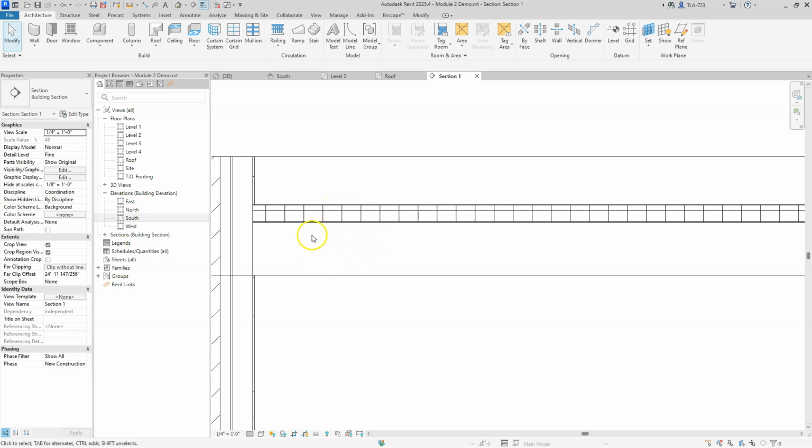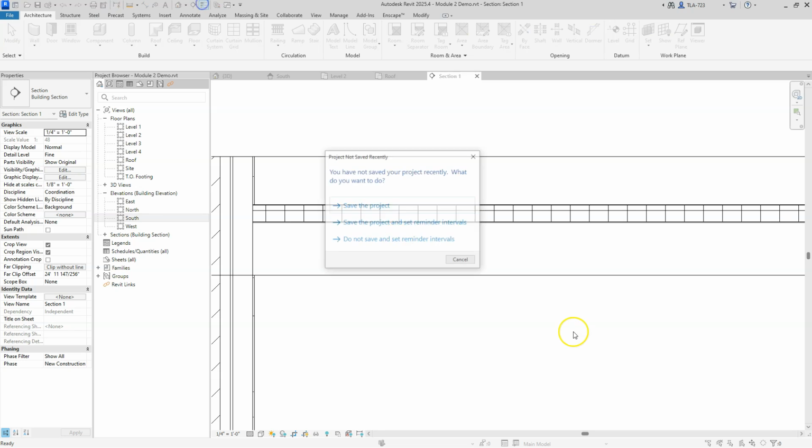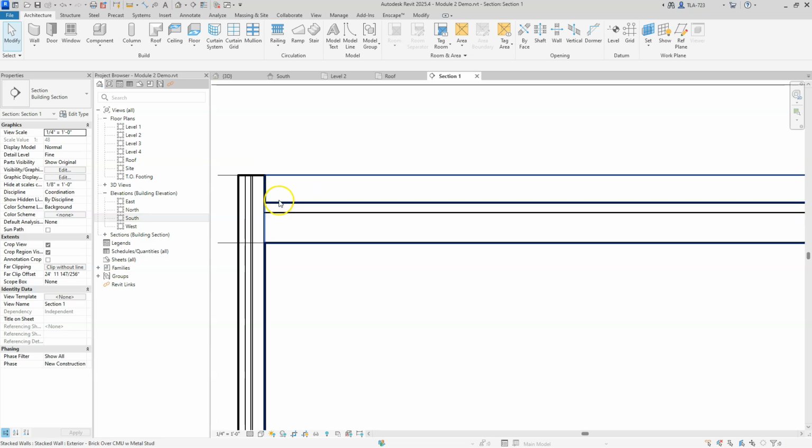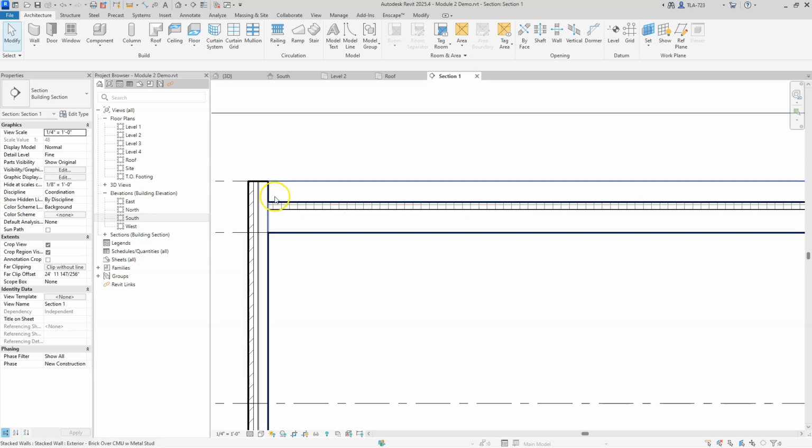So down here you have the roof structure. I'm going to turn off thin lines for a second. Down here is the roof structure from here to here. From here to here, this hatched area, that's actually rigid foam insulation. And that rigid foam comes in sheets that are tapered. Now this insulation might be a little bit too thin. That's probably going to get too thin when we slope it down to a drain, for example.